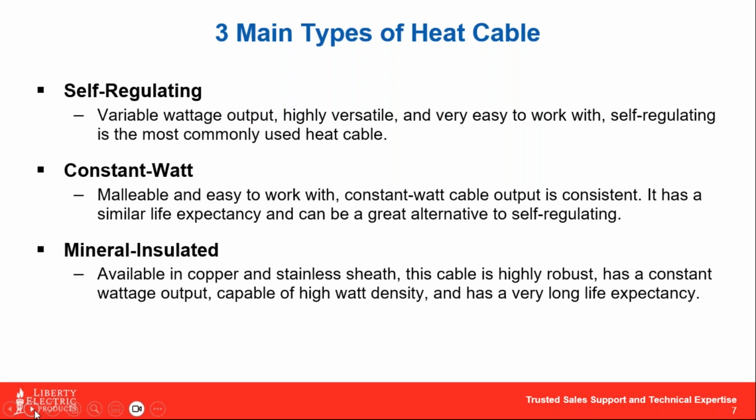Constant wattage cables can be very easy to work with as well. They're easy to splice and terminate out in the field, but they have some different properties that we're going to identify in addition to self-regulating. The mineral insulated cables are also very similar to a constant wattage cable in how they function. These are engineered and produced specifically per application, so they're a little more complex than your standard constant wattage, and we'll get into that in a moment.